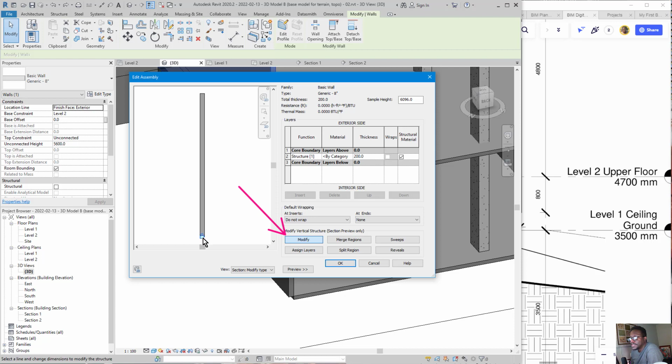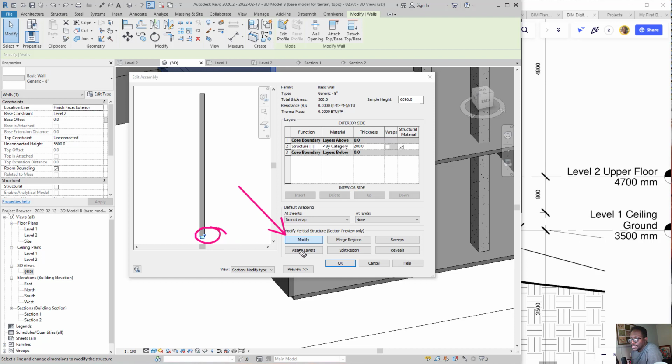You have to hover until the lock symbol turns orange, and you want to just unlock that. So again, all you need to do is unlock it, but you need to click the modify tab first, right? Then you're going to hover over that baseline and just uncheck that lock.